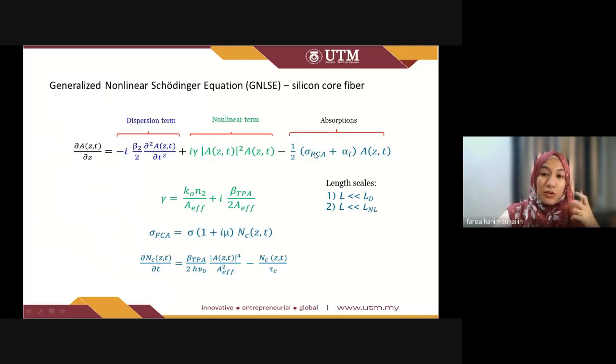Absorption can be linear or nonlinear in optical fibers, where the linear term is, of course, for material attenuation, for example, but another term is related to free carrier absorption, which is the absorption of photons by free carriers making interstate movement inside the conduction band, for example, and they absorb an additional photon for that, which can induce loss.